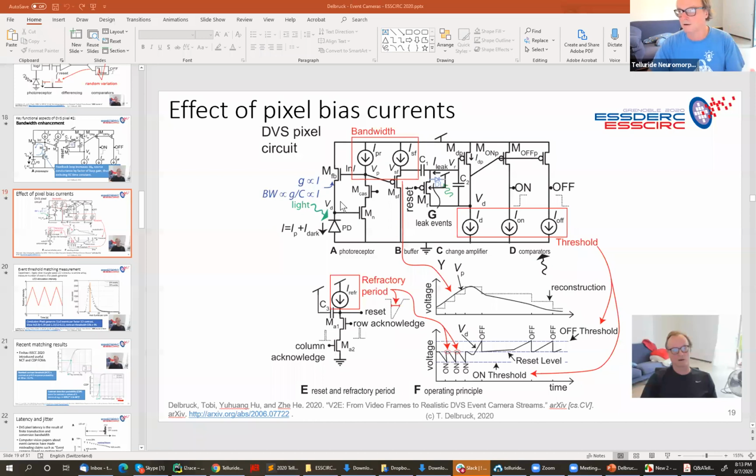Now, what you don't understand, because you're not an image sensor designer, is that the fixing of the parameters of an image sensor initially was just like these neuromorphic chips. People had to fiddle around with the biases. If people remember the days of tube cameras, they had these very complex, like 15 different potentiometers that had to be carefully adjusted to control the biasing of these tube video cameras. The same with early CMOS cameras, they had lots of complex biases.